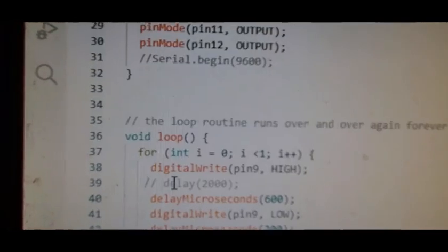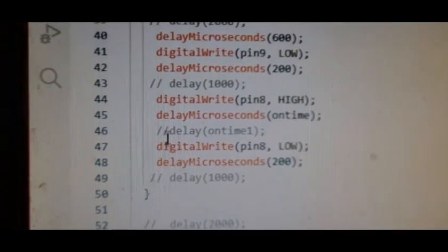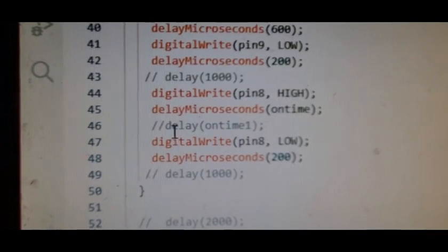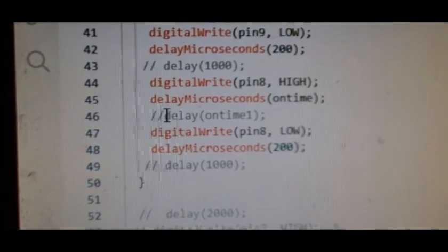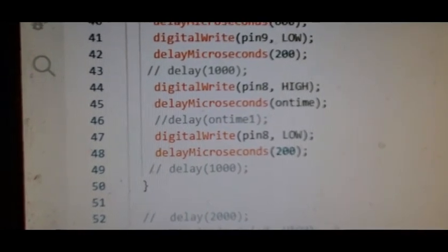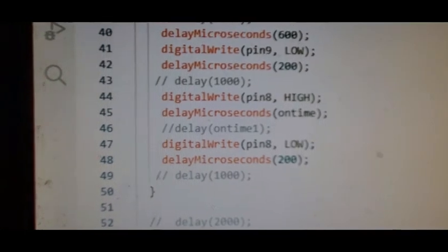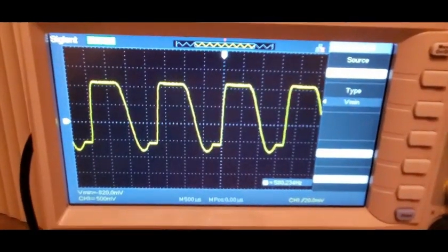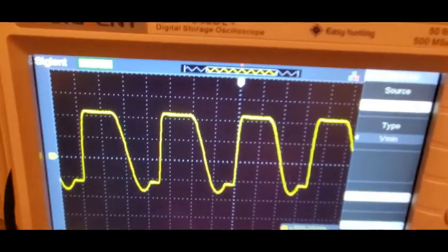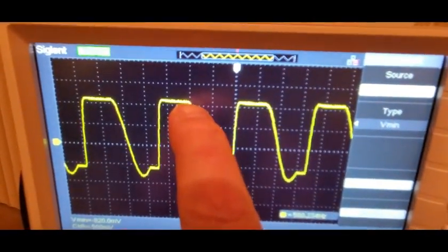And we don't want to run it as a bell ringing, so we got rid of the delay on time already. So if we recalibrate, so you can see on the oscilloscope what I'm talking about. So this is actually that 500 microseconds. It's just showing the cap has plenty of time to charge.